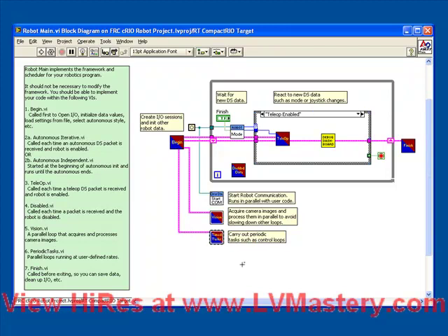So what we're going to do in this exercise is take that sub-VI which we created in the previous exercise to drive that mechanical lifter, take it out of Tele-Op, and actually turn it into a VI which we can run right at the root of robot main, so that it will have deterministic, accurate, and fast timing. Let's begin with the obvious approach.